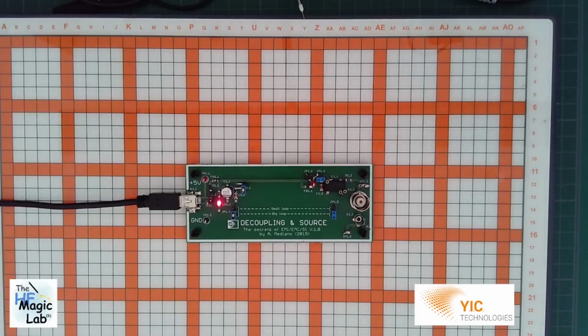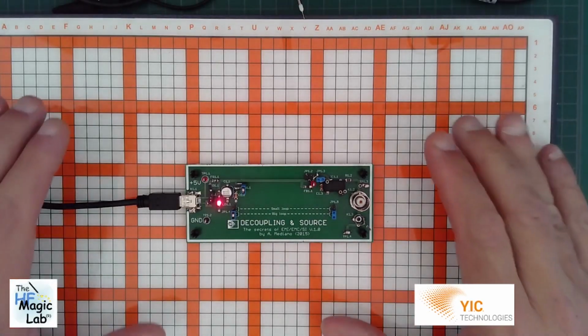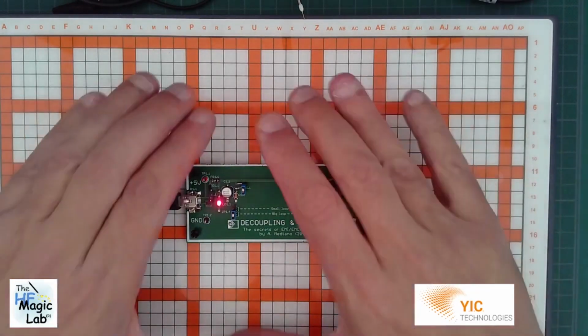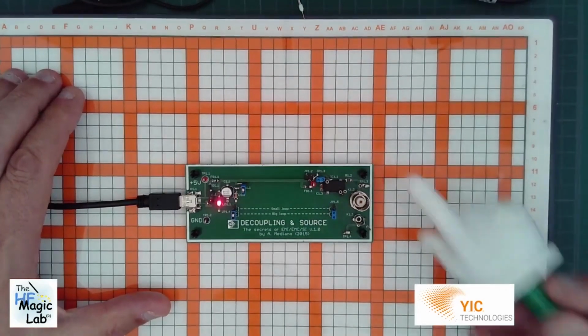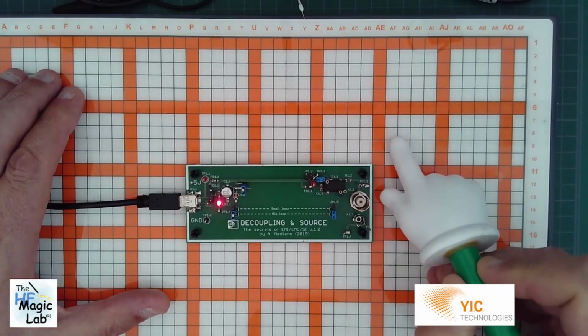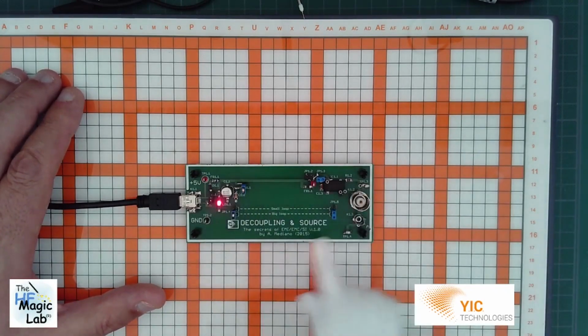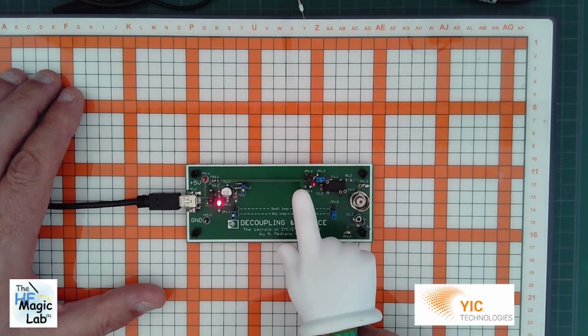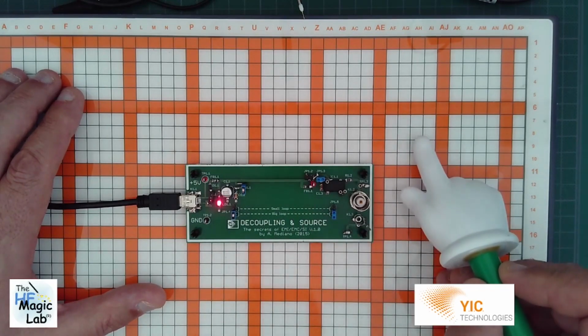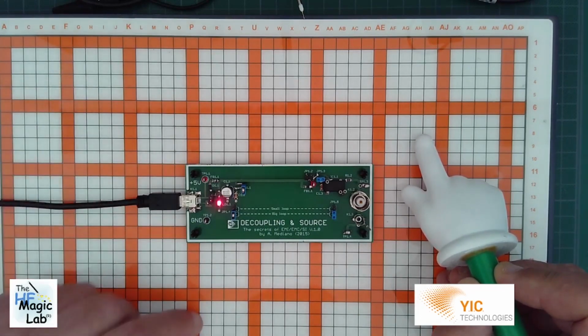Well, so let's see how we can scan the PC board. To scan the PC board, we need the EMScanner. You can see that it is a flat surface, and we can find different cells. Below each cell, we have two small, very small near-field probes. So we have a high spatial resolution. In high resolution models of the scanner, we can go well below the millimeter if you are interested in very small PCBs or integrated circuits.